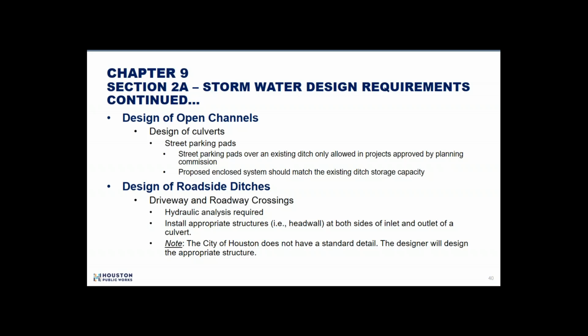If you eliminate storage in that system due to that parking pad, it will have to be recaptured in an underground system. So you may have to put in boxes, multiple pipes, or some kind of system to accommodate all the storage lost in that system. That was one of our biggest issues with the roadside ditches right now, and especially all the redevelopment, is the elimination of storage in the system. It's pretty bad. This is an attempt so that if you're going to develop this corridor, you're going to have to, at the minimum, start restoring lost storage.